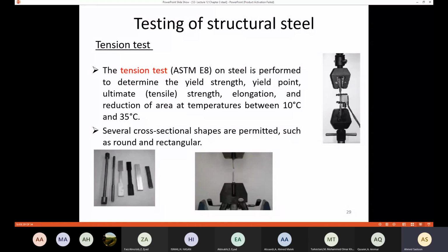We also need a load cell in order to record the load, and maybe an LVDT in order to determine the elongation. All of these values should be recorded so that you can generate the stress strain diagram. You are going to apply a force up to failure.